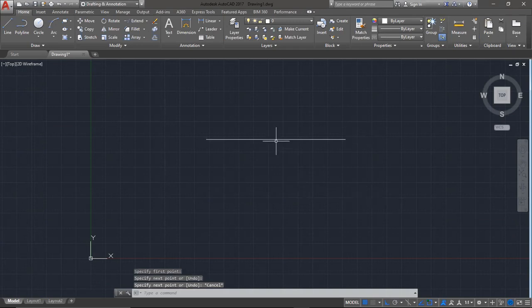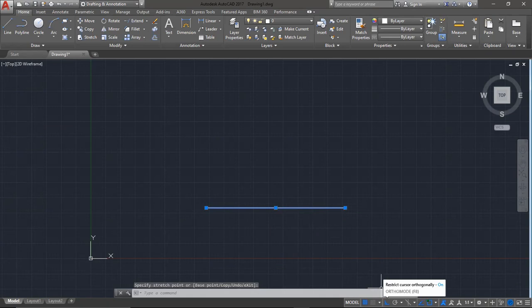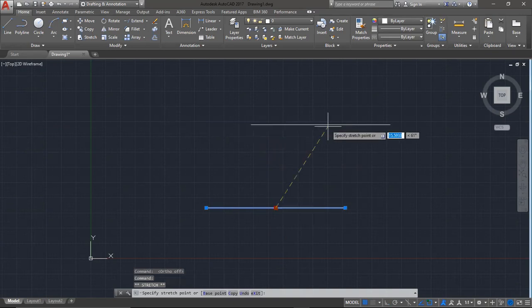like that, if I select that line, you realize there are some grips that will appear as boxes here, here, and here at the end. These are called grips. I can also use them to maybe move. Like if I use the middle one, I take my cursor there and I don't have to drag, I just have to click once and I can move. And then I can move it there. So you can see it is moved. I realized my auto mode is on, and let me turn it off and now move it again. You can see I can move it anywhere. And then when I'm done, just click.